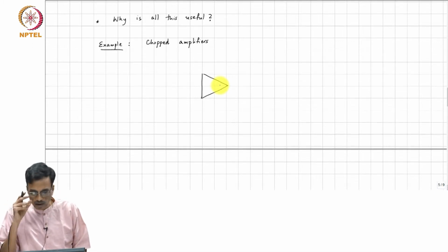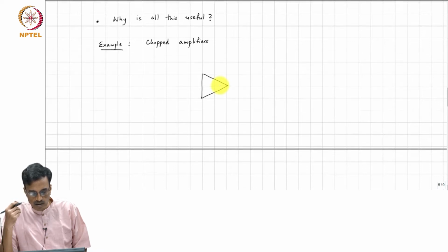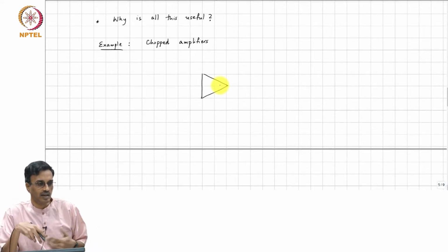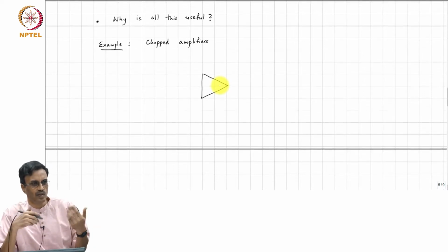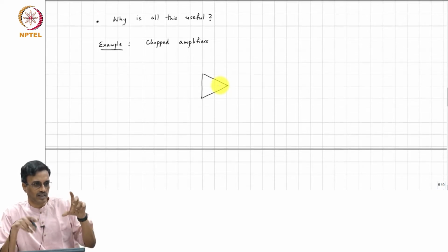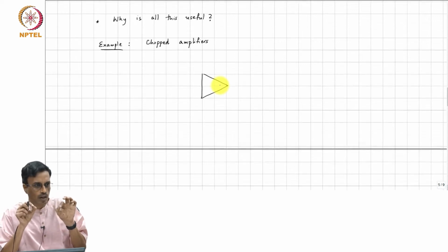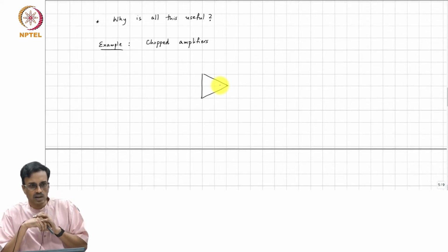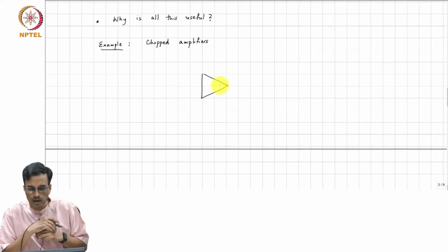If you were trying to measure a very small amount of weight, for instance in a precision balance, this is mostly done using Wheatstone bridge kind of sensors. You have strain gauges, and you are trying to amplify a very small difference in voltage, and of course this voltage is a DC voltage and needs to be amplified.